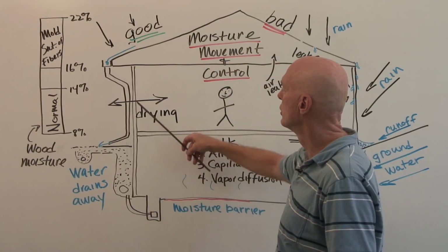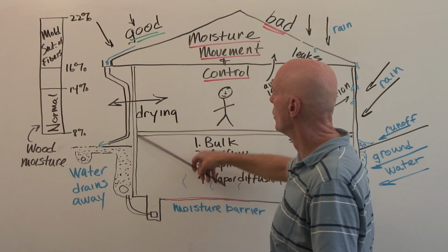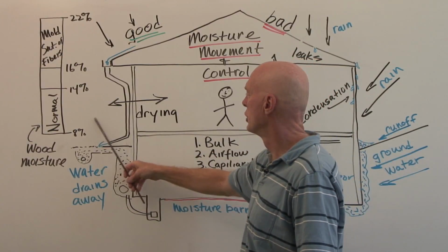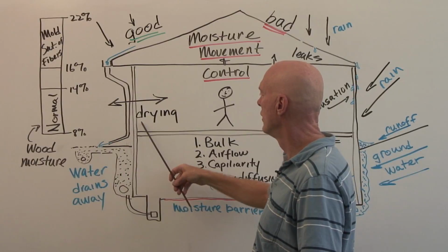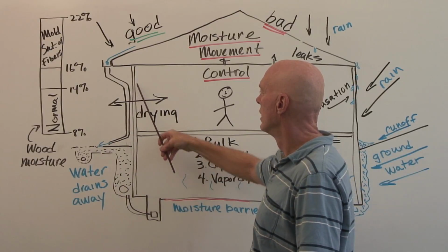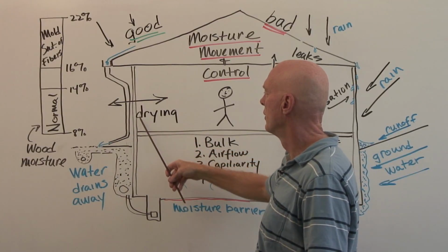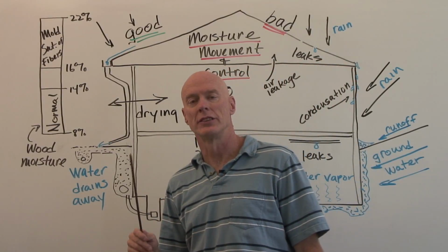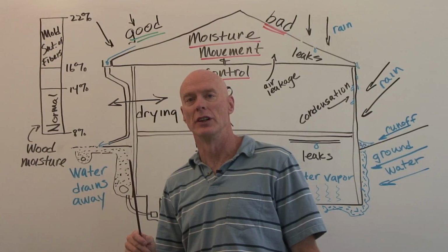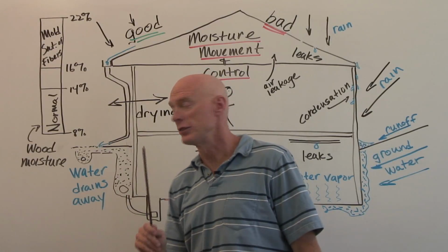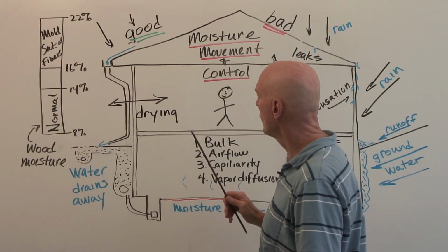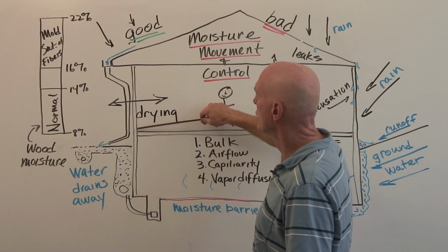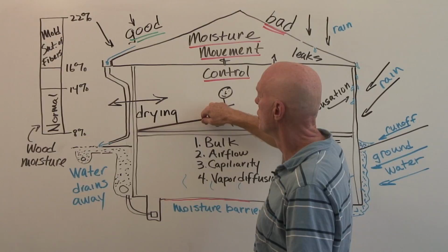And the reason is, with a vapor barrier in the wall, if you're air conditioning a building, the moisture can be traveling from the outside to the inside. It can get caught here at the vapor barrier. That's when water can condense and wet the insulation materials and the studs. So if we don't have a vapor barrier, and then there's a number of different types of vapor barriers.